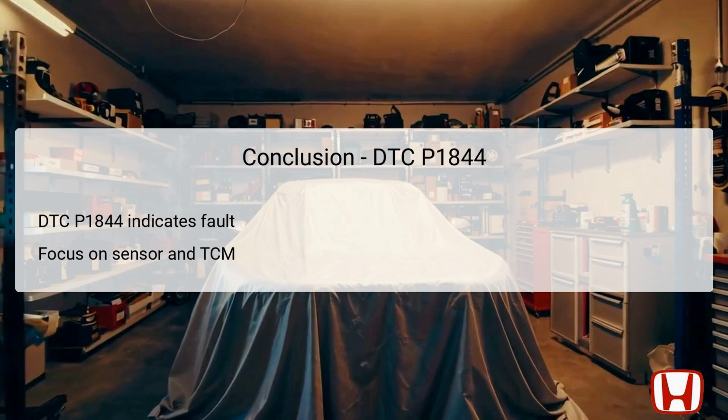In summary, DTC P1844 points to an issue within the CVT input shaft speed sensor circuit that affects forward rotation detection. By taking a thorough approach in fault diagnosis and addressing both the speed sensor and TCM, one can effectively resolve the issues signaled by this code. The troubleshooting steps clearly outline the proper procedures for verifying the performance and functionality of the transmission system. Attention to preventive maintenance practices will help reduce the likelihood of encountering similar DTCs in the future.